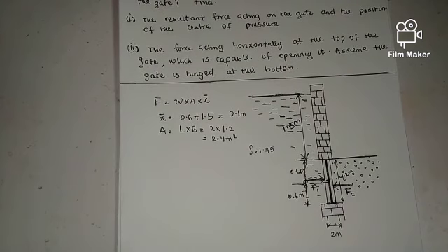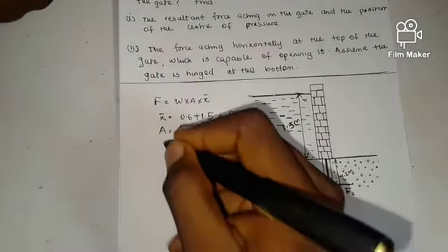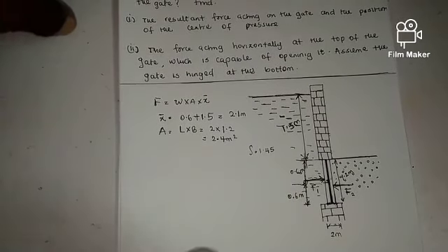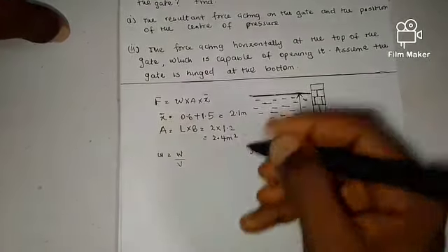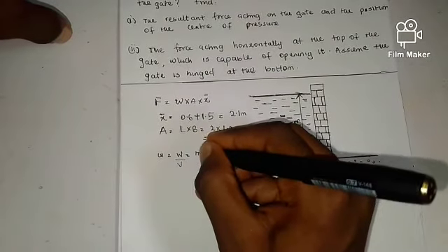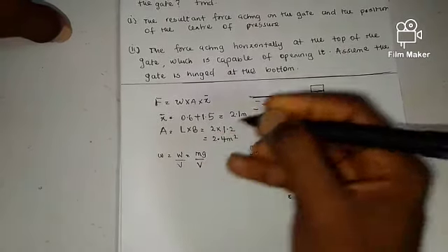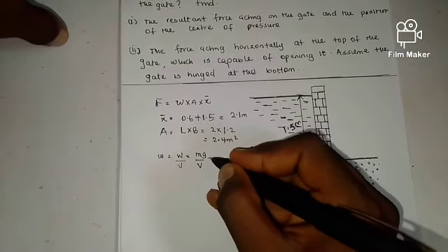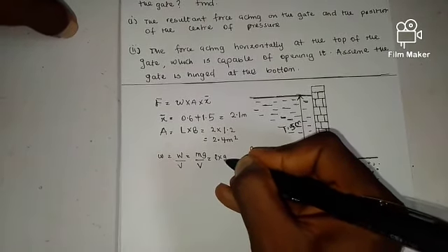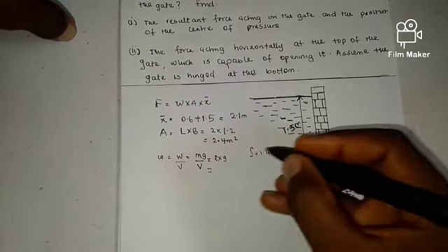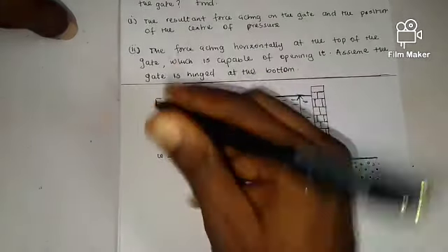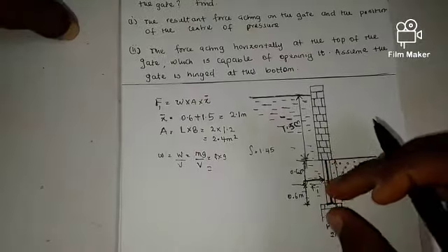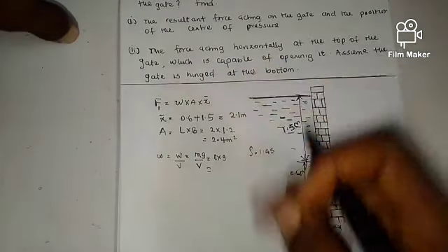Then next stop is our weight density. Now what's our weight density? Our weight density is the weight divided by the volume, which is mg divided by v. You know that density is mass over volume, so I can basically write it as density times g, right? Now remember I'm basically considering this first part of this fluid, which is F1. I want to calculate this F1, right?